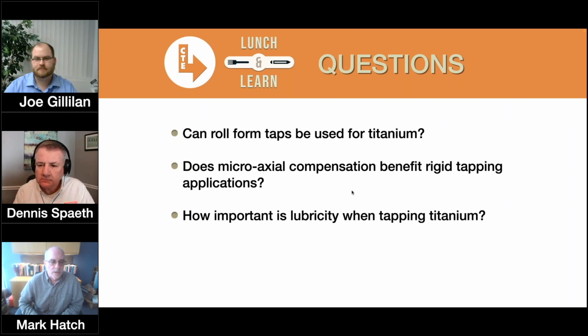It's been well known. I may be showing my age, but back in the 1990s, when synchronous tapping was starting to take off in the machine tool industry, it was learned early on that although they were a major improvement over conventional tapping, they did not solve all the answers of tracking the spindle and the slide precisely to the tap lead. So this is why it's important to have this separation from the spindle and the slide, with these micro adjustments to make for these small errors.